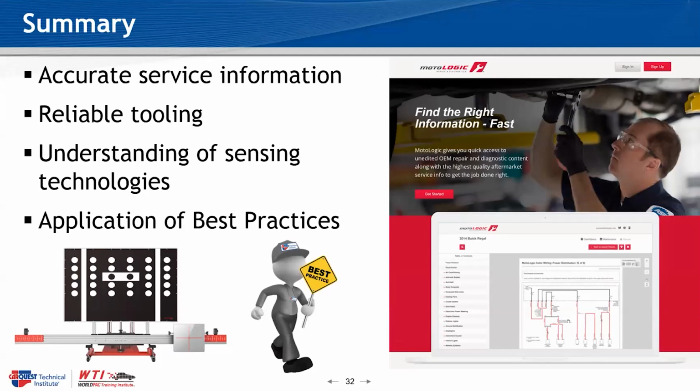Maybe we didn't directly adjust thrust angle because of the tire pressure, but we changed a lot more than that with the tire pressure. We actually changed more than one axis of movement. We went down and to a direction. So it's way farther off than it would be just with a thrust angle. So those are all things to play into that.